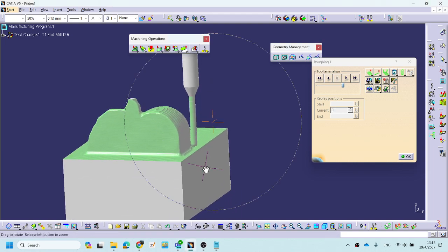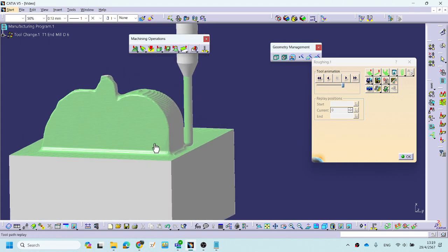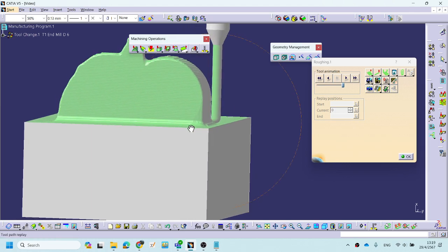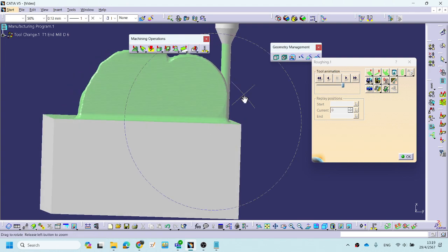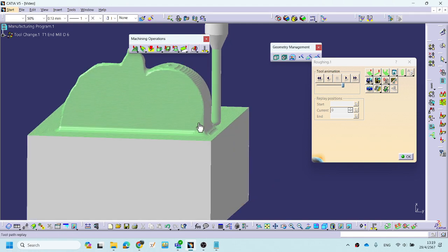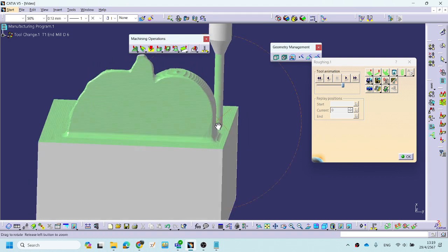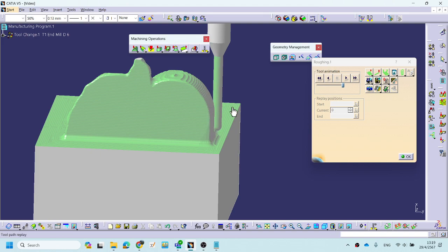So in this step, you see, before I simulated the tool path and generated the G code, right? There is a part like this, I told you before, and this shape could not quite undercut the surface, and it is still straight, the shape is vertical, right? Because the tool cannot move along its y-axis, and the cutting tool goes along and around the z-axis.